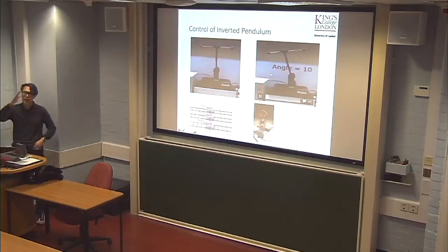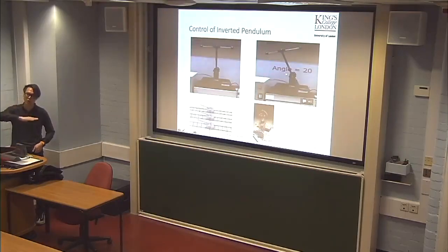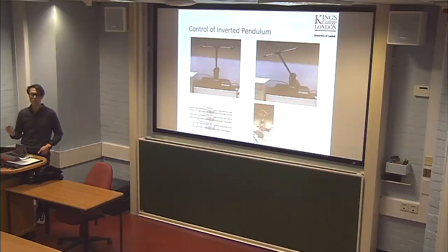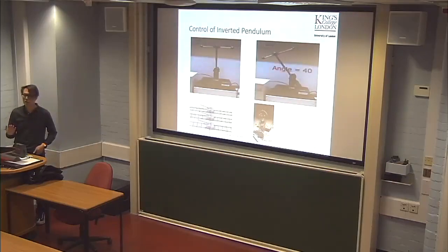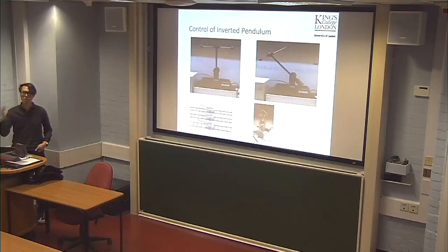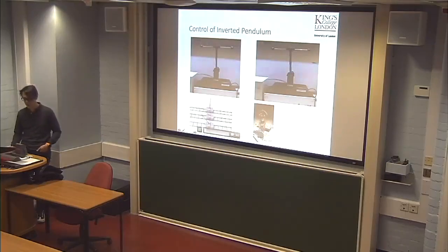We would like to hold a given angle for the pole. Now you can see that we keep the angle at 10 degrees, 20 degrees, 25, 40, and so on. If you use a linear PID controller, in my experience, it doesn't work when the angle is more than 20 or 25. It is mainly because the linear controller does not consider the nonlinearity of the system. But when we consider the fuzzy model as well as the fuzzy controller, we address all this nonlinearity, region by region. Now in these two applications, I do not consider performance. If you really need to consider the performance, then we can consider this application as well: the cart-pole inverted pendulum.